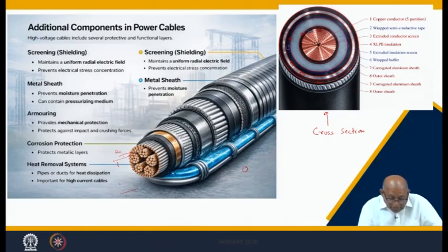Everything is grounded in a mining system. So this is high voltage. If you divide by the distance, there is an electric field gradient. Electric field is essentially the voltage gradient with respect to distance, ∂V/∂x. That means voltage by distance, differential voltage. This electric field is essential for creating all kinds of damage. Electric field is responsible for breakdown.